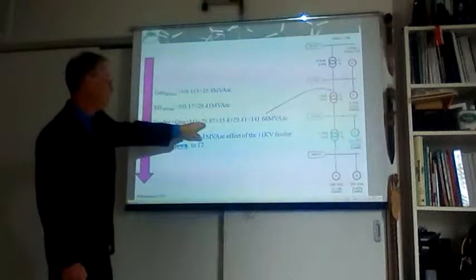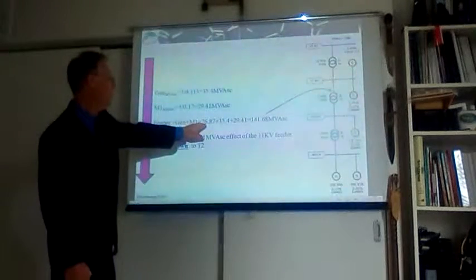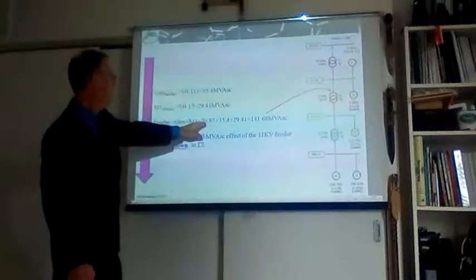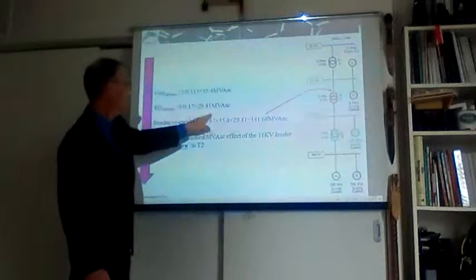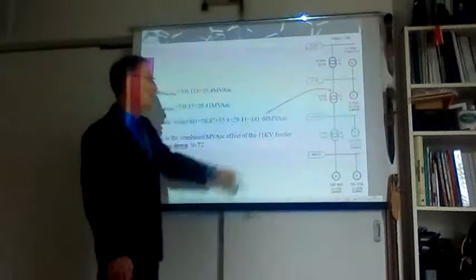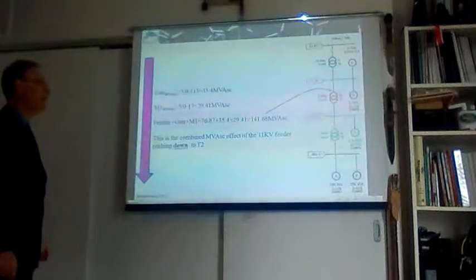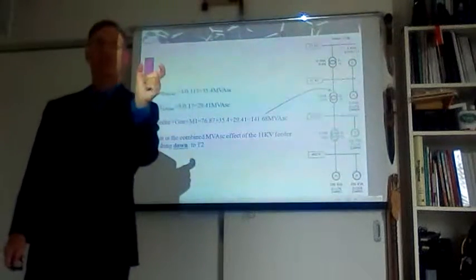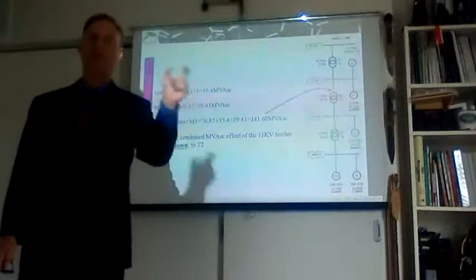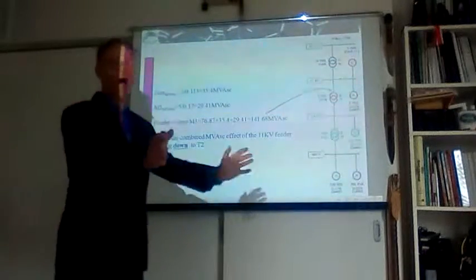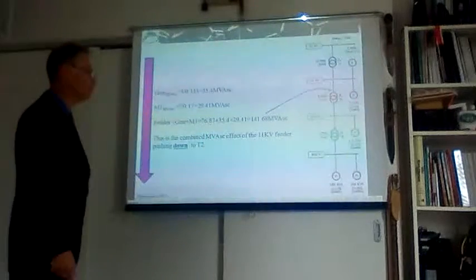And we add them together, the 76 MVA that we calculated here, plus 35 MVA, plus 29 MVA from the motors, will give us 141 MVA on the short circuit in the first 2-3 cycles. That is the shock that the system will see.